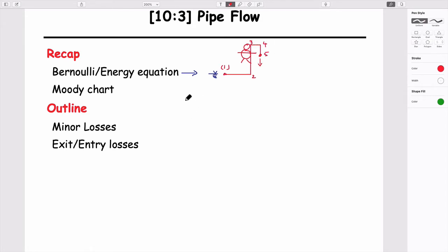And we'd write an energy equation, which is the one that we want, which is merely the same form as we've had before. Elevation plus pressure plus velocity head plus pump head has to be equal to the same components, in this case at 5, if we write it between those two, plus two sets of head loss equations.